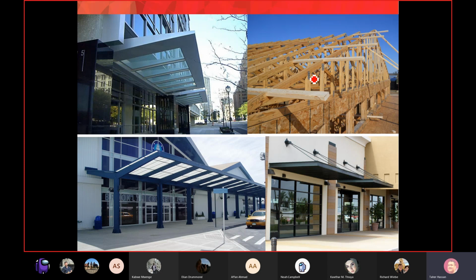What you see on the top right picture here is, I would say, maybe a house or maybe a wood building. It's not a house; it's a wood building, and this wood building is still framed, not covered yet, where you can see trusses. So those are roof trusses. And typically for wood structures, we have an eave overhang, something that extends outside the building by roughly about 2 feet. And this is the way you frame it.